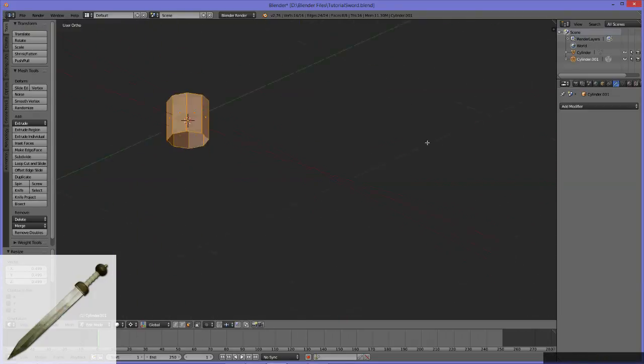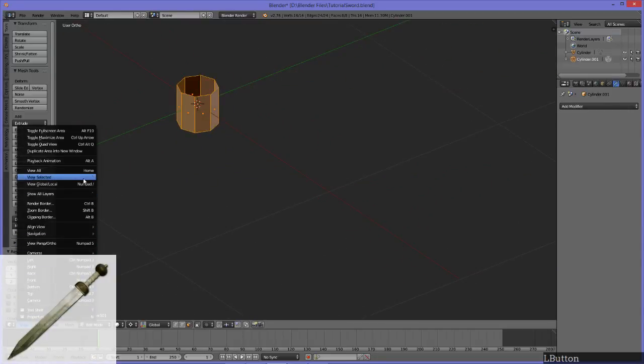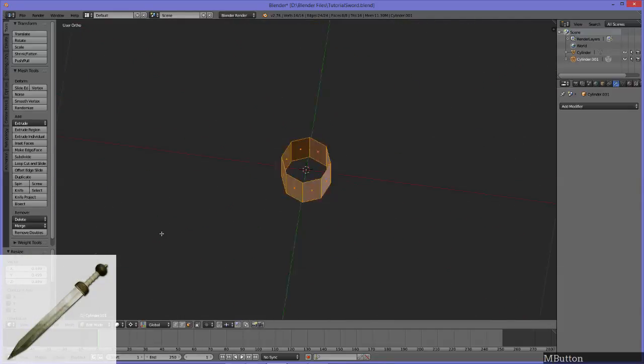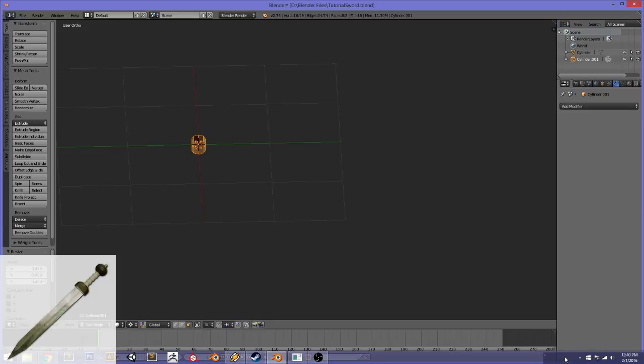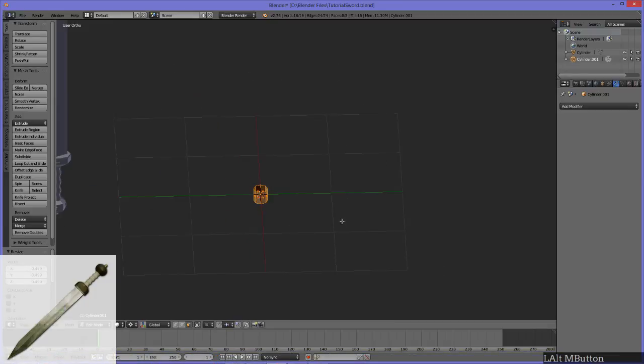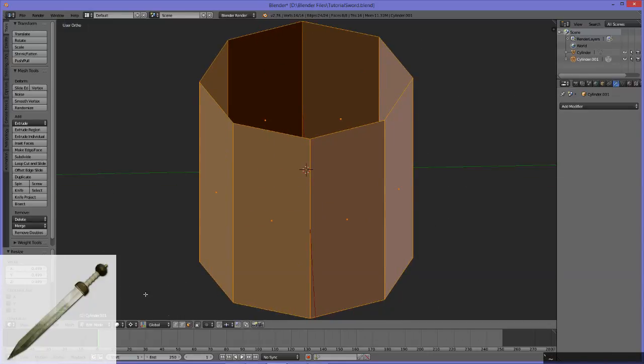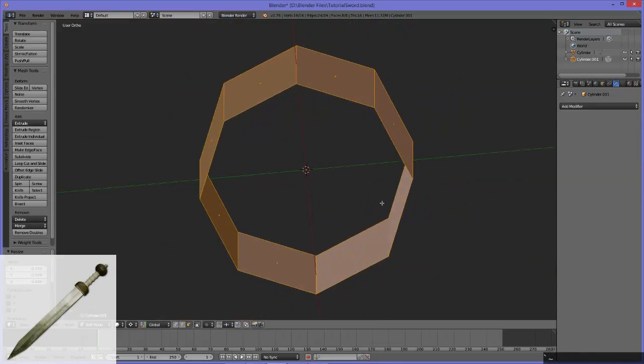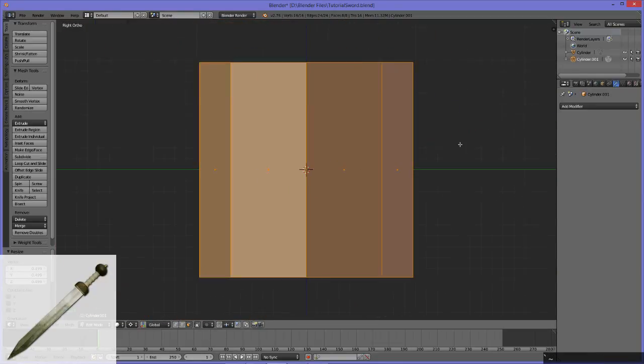You see that we're not centered on it, we're kind of floating around in space. You can go to View Selected, and that'll zoom you right in and focus you right around the object, so it's right in the center. I also have this bound to a hotkey. I have it bound to my tilde key. If you see down here, that little marking right there is tilde. Whenever I press that and I'm in this 3D window, I will always recenter on it no matter what I do.